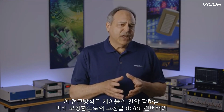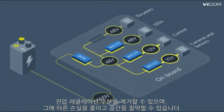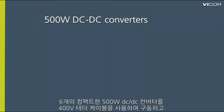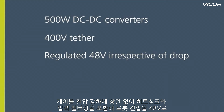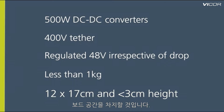Since this approach compensates for voltage drop on the tether up front, the voltage regulation part of the high voltage DC to DC converter can be removed, reducing related losses in space. Another comparison to consider is that an array of 6 500-watt compact DC to DC converters powered from a 400-volt tether and regulating the vehicle voltage to 48 volts, irrespective of tether voltage drop, including heat sinking and input filtering, would weigh less than 1 kilogram and take up a 12 by 17 centimeter board space with a height under 3 centimeters.